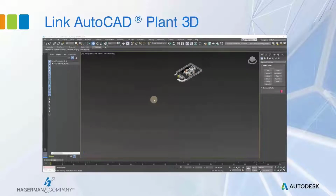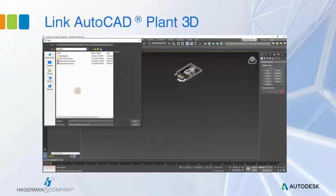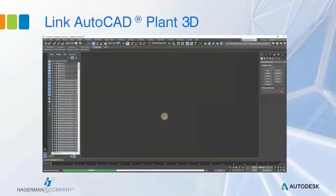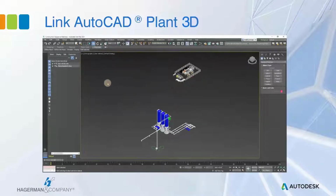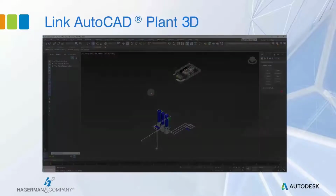Next, we'll bring in the CAD files. We'll start with the Plant 3D model first. And I'm going to link this CAD file versus import. Linking does come with some presets. And you'll also have control over which layers you would like to bring in. So you can bring in only portions of a CAD file if you want. Now this file, the actual project position was accounted for while it was being modeled, which means it will land where it's supposed to in Max. Again, the file was grouped automatically. That'll make it easier to work with.